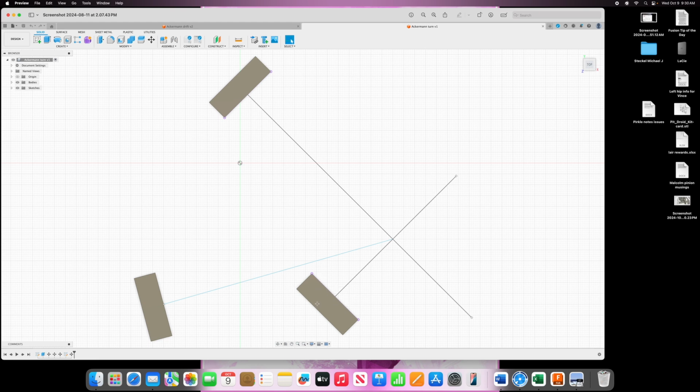I'm going to do the same on the inner back wheel. So the inner wheel, as you're turning the corner, it's going to do the exact number of degrees as the front wheel, just in the opposite direction. So that's how I'm planning it for right now. This will all be subject to testing once it gets built and goes out there. So, linear function here, duplicate this in the opposite direction.